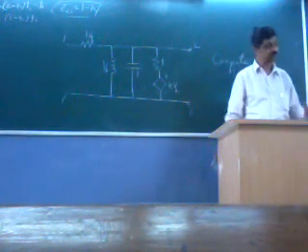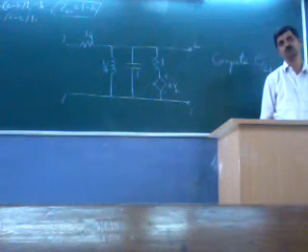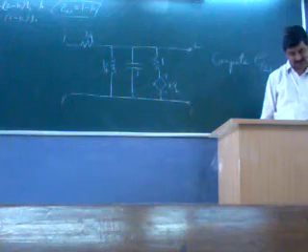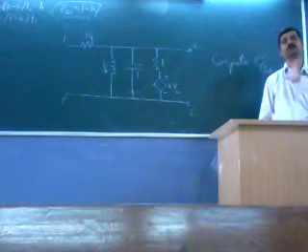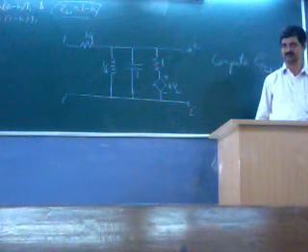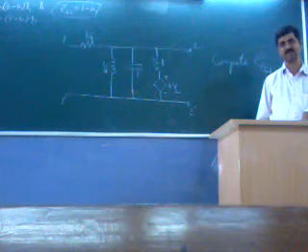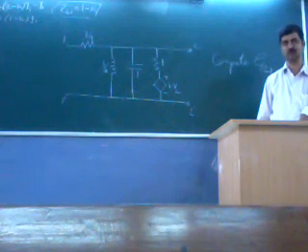So ultimately, for a voltage or a current source of the type e raised to st, we can compute all these parameters. These describe different network functions, which are ratios at the same port for driving point, or the cross ratio, from the other port to this port.